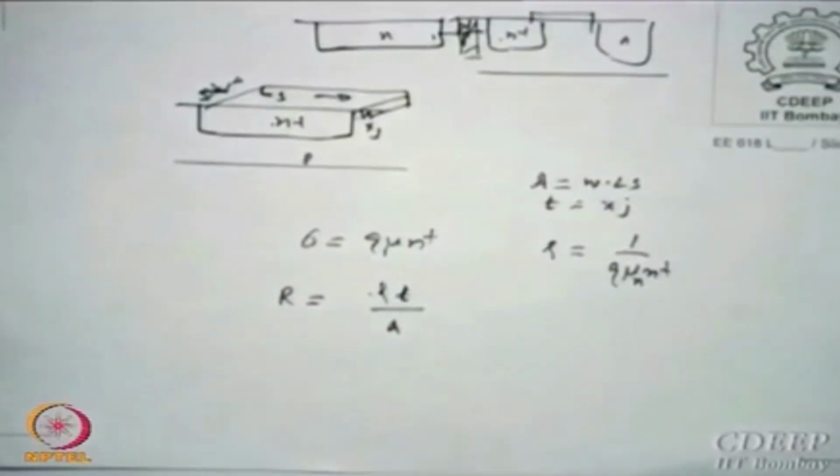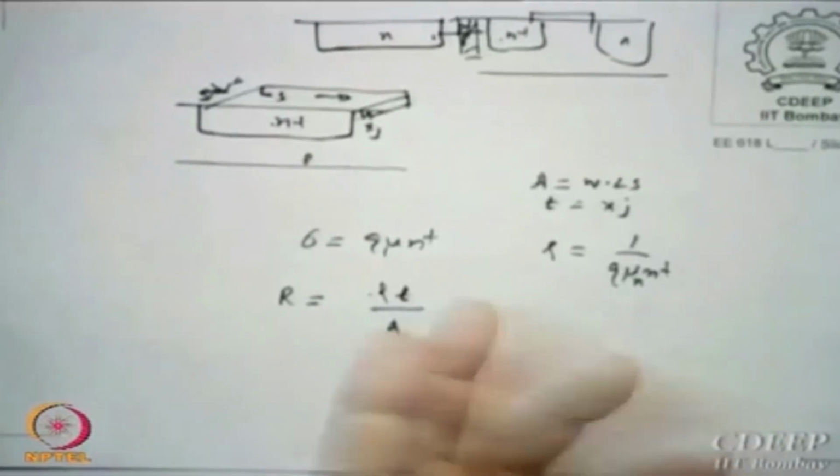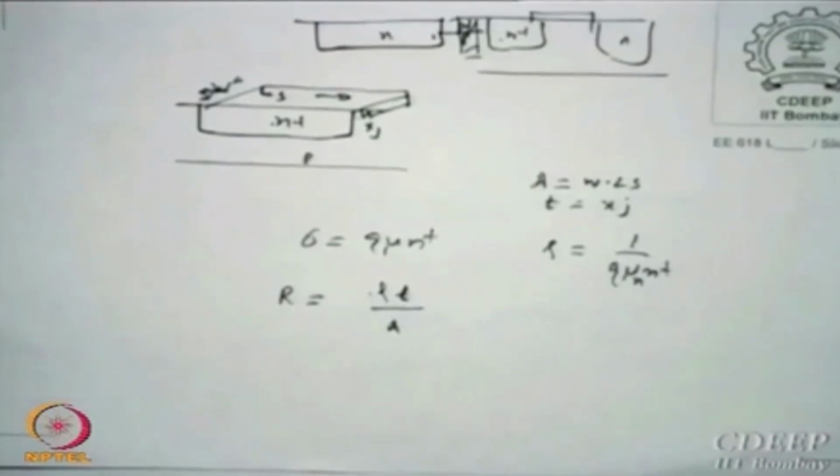It is called a guard ring. So put either a guard ring or isolating oxides below, trench it down and separate the two areas. That is the basic requirement to make any other component. So every component in a circuit has to be isolated from the others by either of these techniques, and that costs a hell of a lot of money.